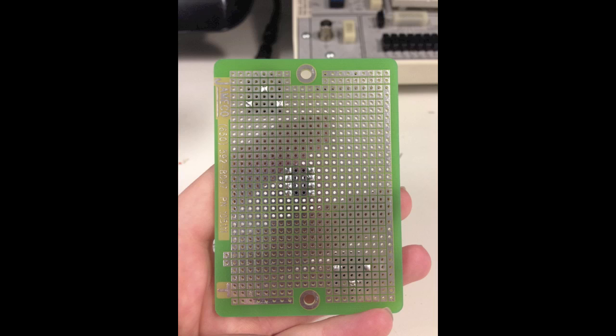Another thing to notice is that the board's a little different from the breadboards that we're used to using. On the breadboards, we had nice little rows and columns throughout the board that would be shorted together for us, and it was pretty convenient for connecting things in series and parallel. This time, you have to take care of the connections for yourself. There are a few places on the board, near the screw holes or on the perimeter of the board, that have a few of the metal pads shorted together, but in general, all the metal pads are separate.